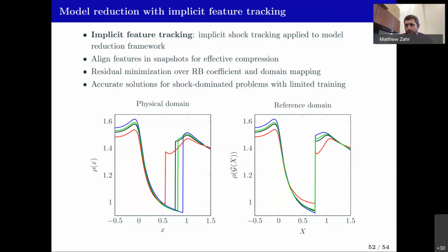And then the second part of the question is how to choose that regularization parameter. There's a little bit of tuning involved with that, but what we do is we adapt it. Actually, we have a few different parameters in here, and they adapt as they go. For example, this one is how we weight between the mesh regularization term and the other term. We start by not treating the mesh, and we adapt the lambda parameter such that those two contributions are roughly balanced throughout the optimization.